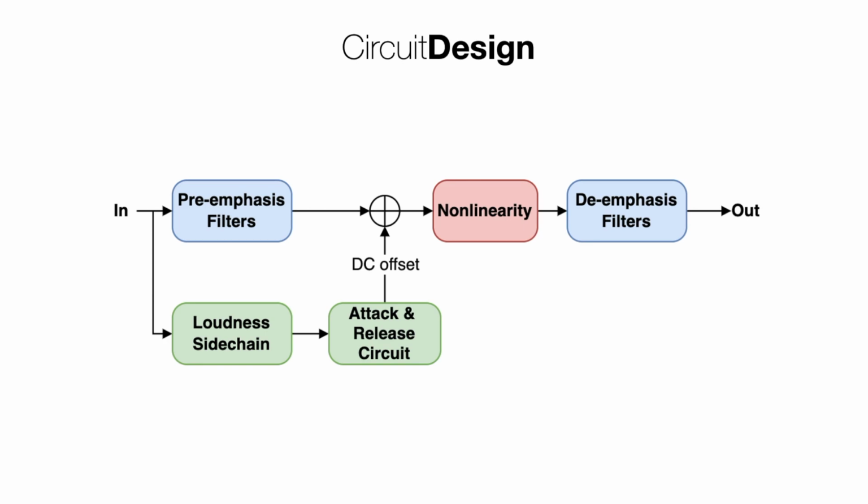The principle behind the characteristic dynamic behavior of this design is similar to those applied for dynamic range compression. The circuit is based on a sidechain that detects the input signal envelope and generates a DC offset at the input of the clipping circuit.